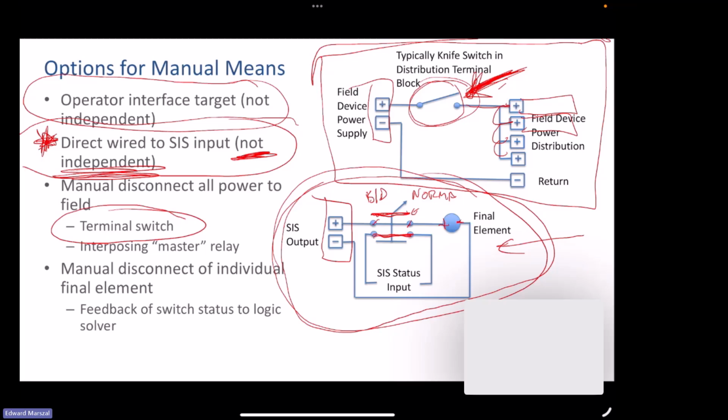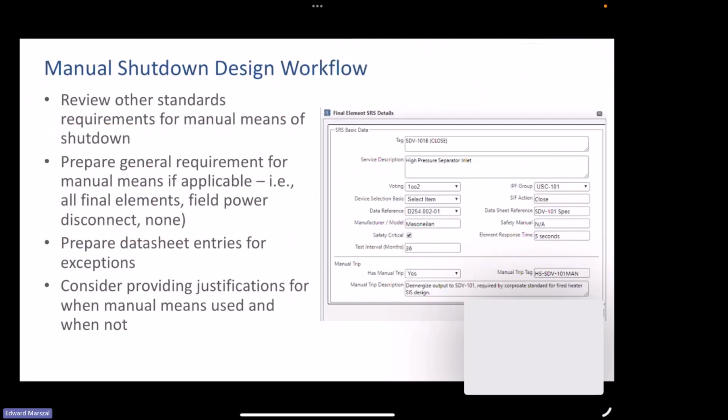Switches just don't open up for no reason. There's a mechanical force that is required to move them from one state to the next. Them just for no reason falling open is a vanishingly low rate, something that I wouldn't even bother to consider in my spurious trip rate calculations.